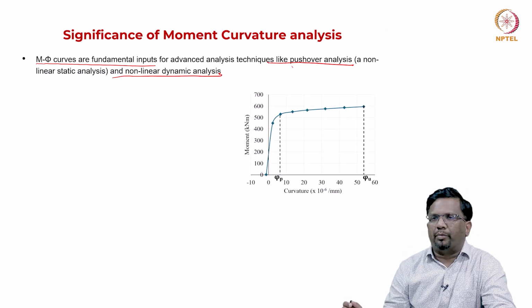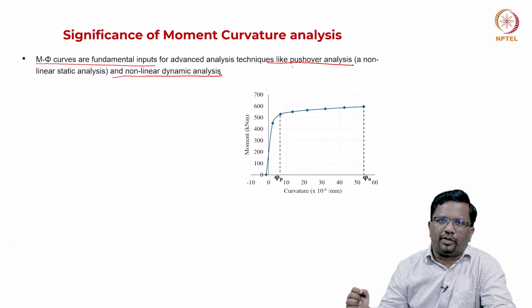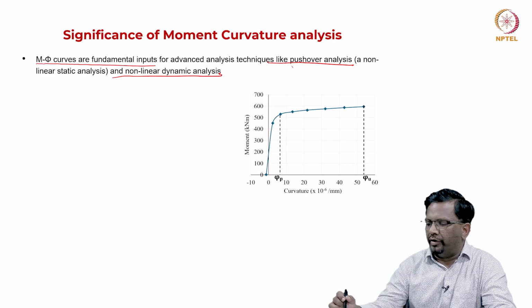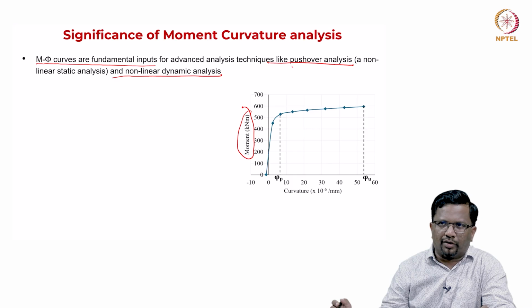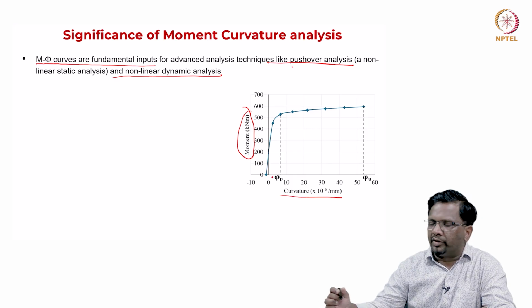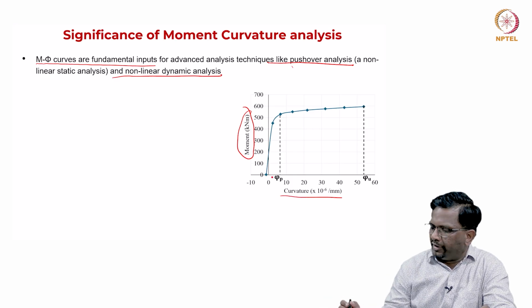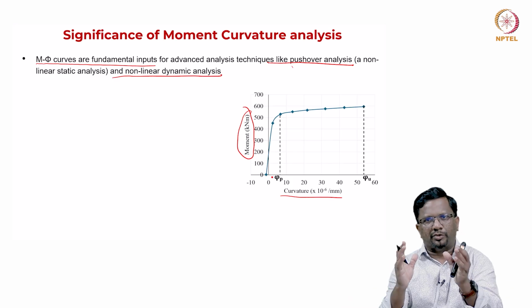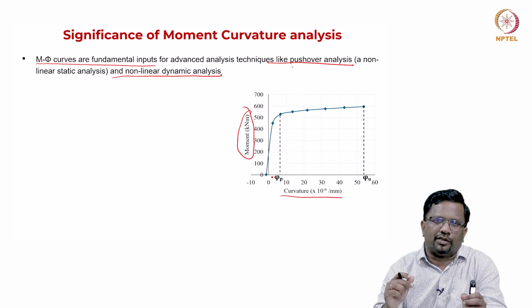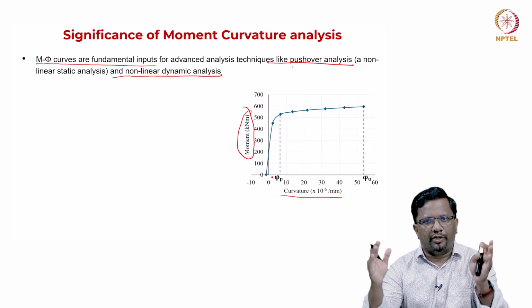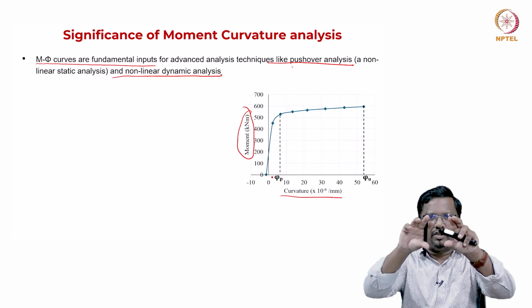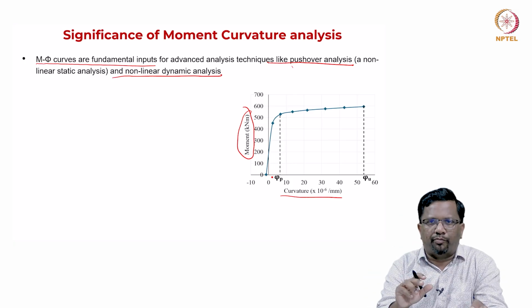So, finally, for a pre-stress cross section, we are trying to get this kind of a behavior where we plot for a particular cross section how the moment and curvature is going to change. You can clearly see here for a pre-stress section, even before any external loads are applied, we put pre-stressing. Because of that, there is going to be a camber upward, right.